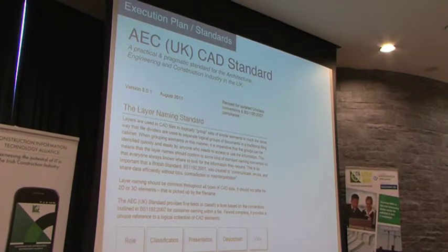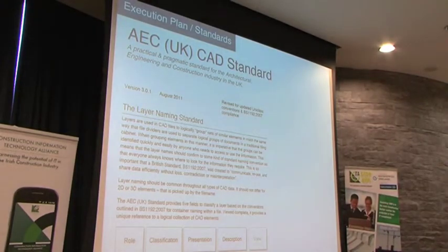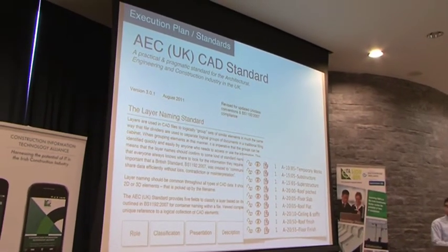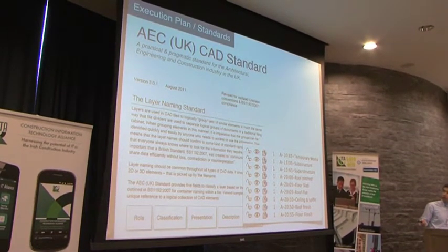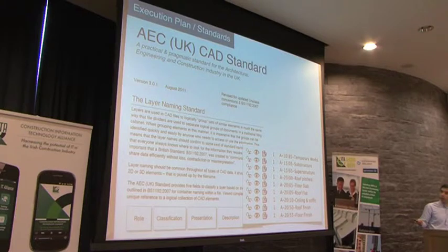Now that's not applicable to all BIM platforms, but for instance, we have set up a whole system as well, a layer set where you can see the originator, architects, the Uniclass 2 coding system, and then the description here. And I think the pilot project is a great example to show how at the very beginning you can start to implement the standards.